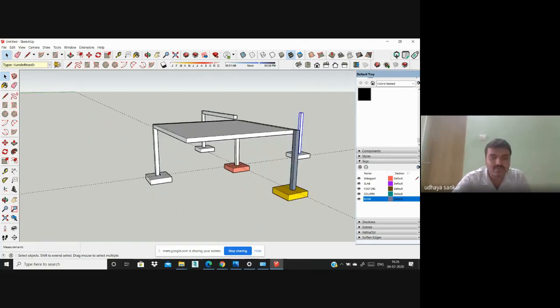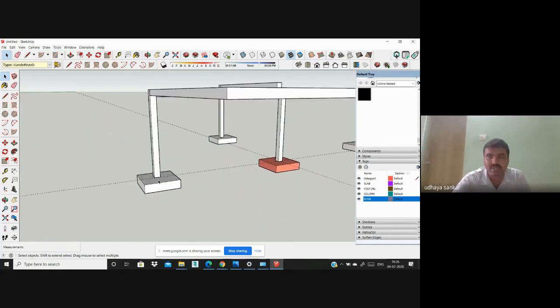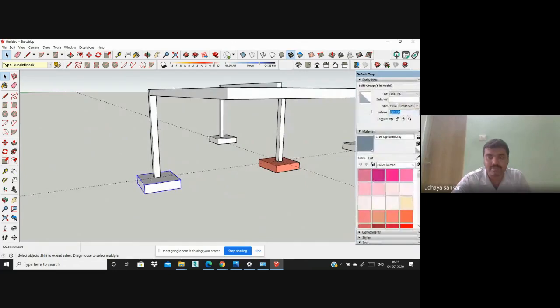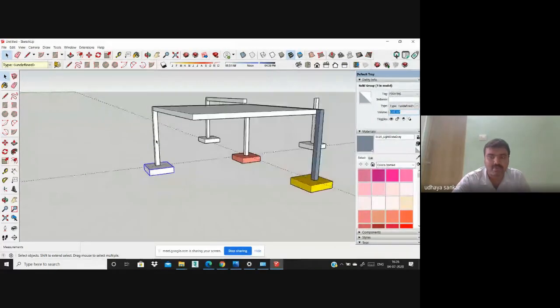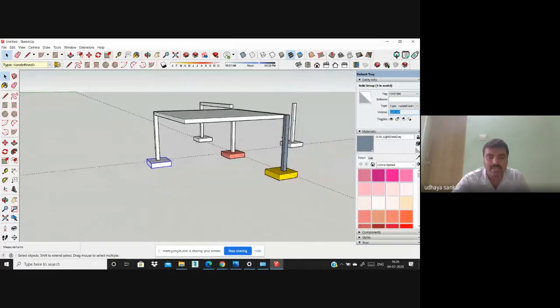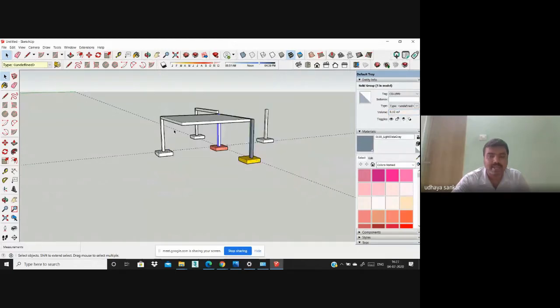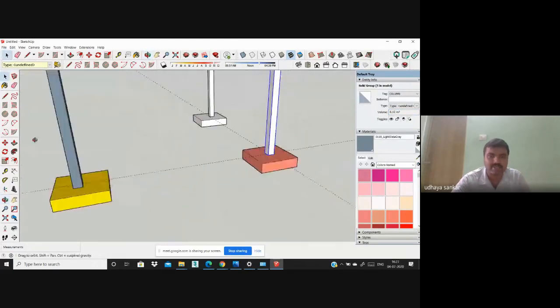This is a footing. I need this footing concrete. You simply select this footing. I need this 0.43 meter cube of footing, multiplied by 4 footings, for the concrete. Multiplied by 4, you calculate the quantity, and likewise the slabs and the beams, etc. Walls are the same.